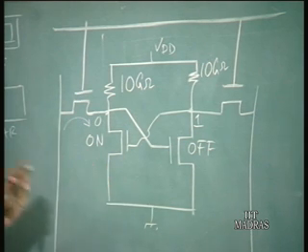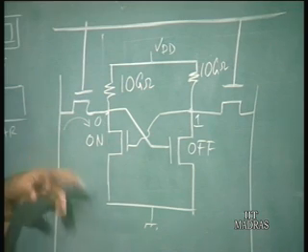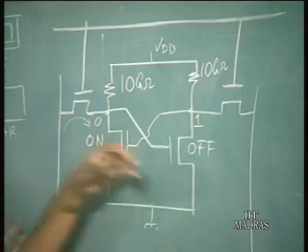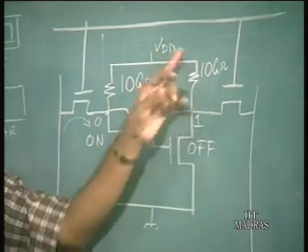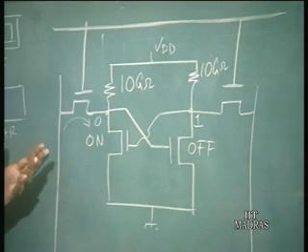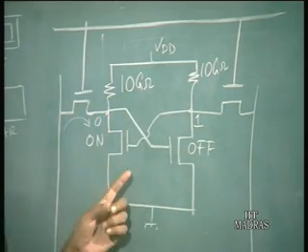So, the pre-charge voltage in this case is going to be VDD, or the highest voltage in the circuit, and then one line is going to be pulled down, the other line is not going to be pulled up. So, you do not depend upon this resistance to pull up. Okay. Now, what is the advantage of having a cell like this, a 4 transistor cell?